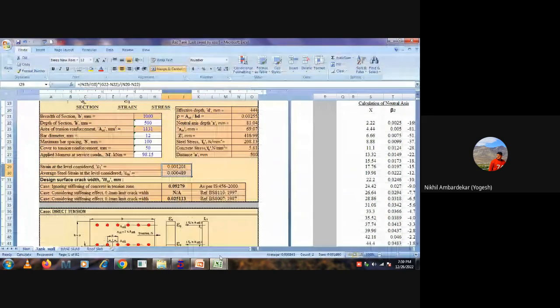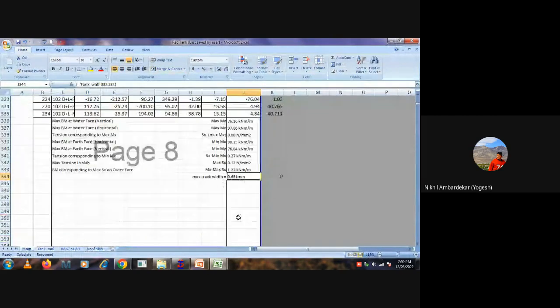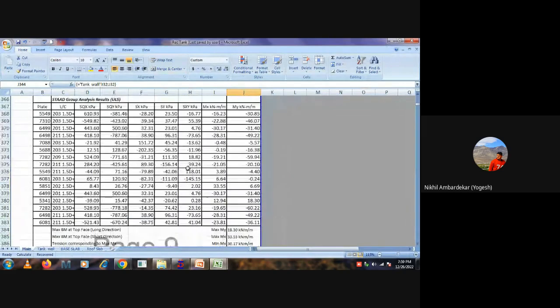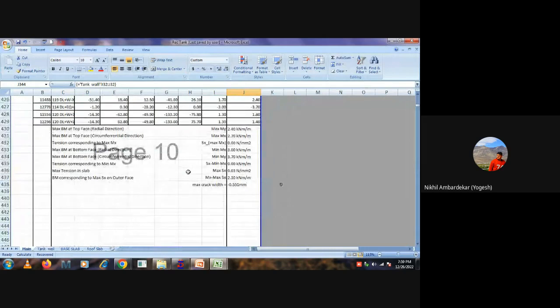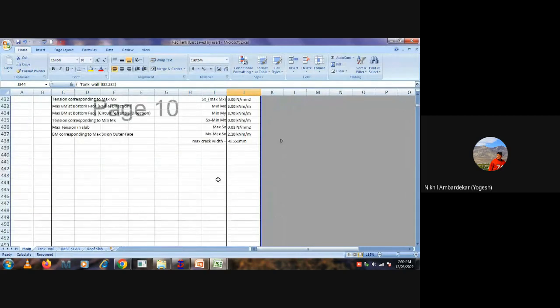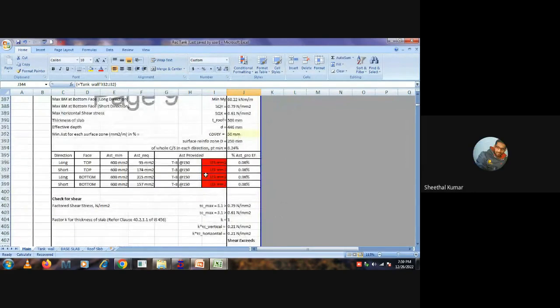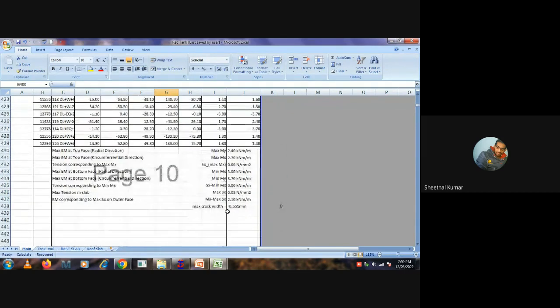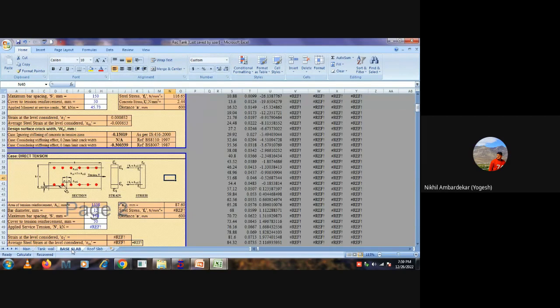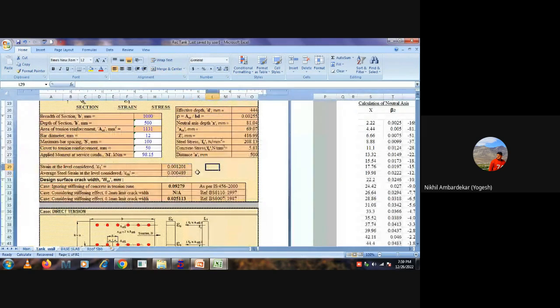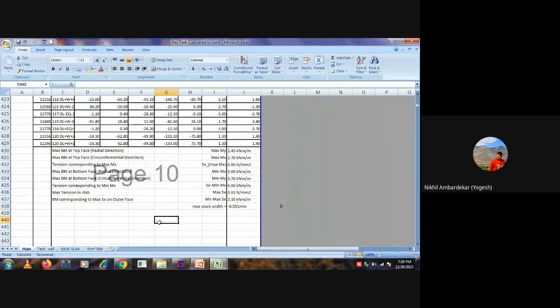But I want to say, if you go here to the main wall, and this crack width is more than that, then what you need to do is update the spacing in such a way that your crack would be less than 0.2 mm. Just check here. Same thing here also. It looks like the formula got changed. That's why it happened, but I will check what happened there. I have the main copy on my laptop, so from that I will pull it out and share it with you. Fine.